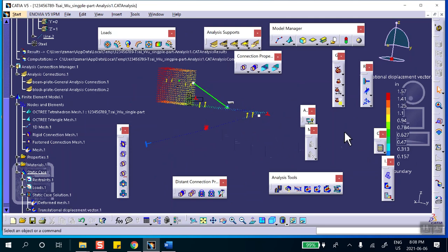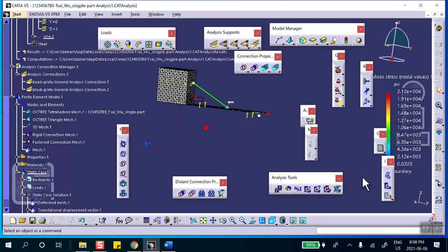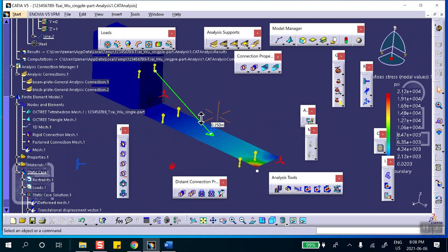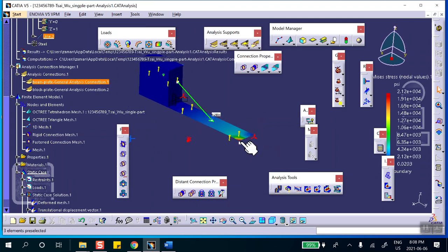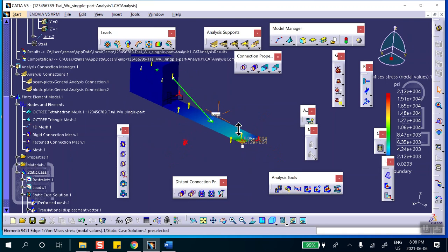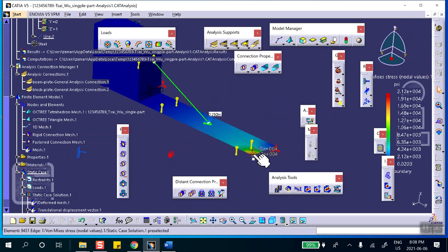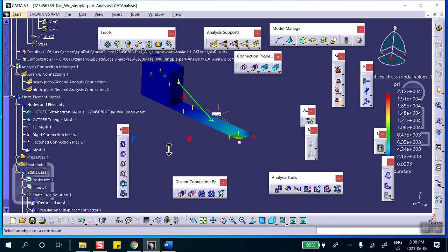I don't think the stress is going to be, well, we have no confidence in these things. You cannot believe these unless you do a mesh convergence study. Okay, as simple as that. Doesn't matter how you slice it. You cannot believe these without a mesh convergence study. Okay, so on the surface, it looks like the place where we have the biggest problem is over here, but there can be. This is on the surface.